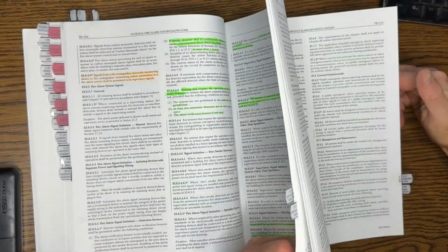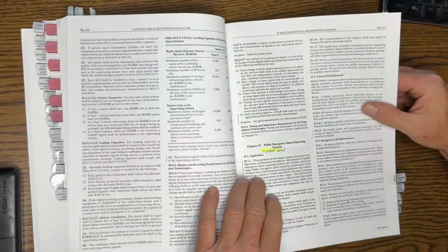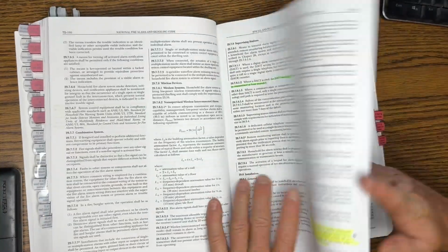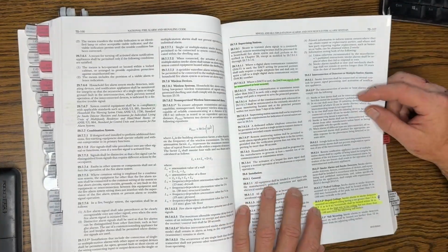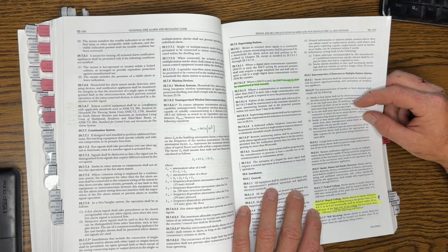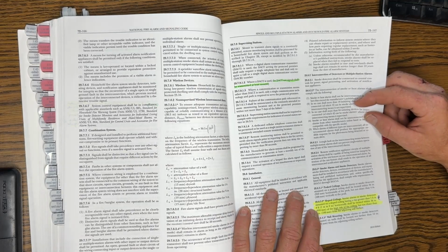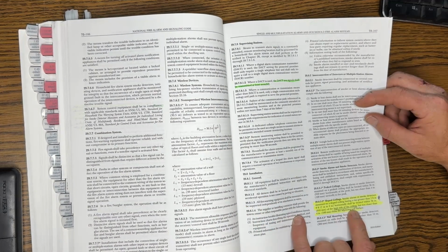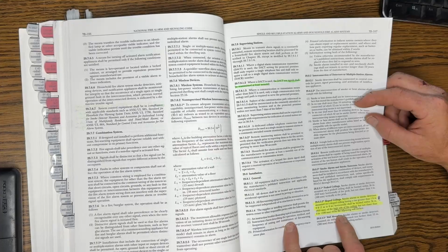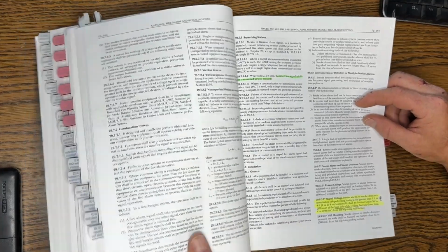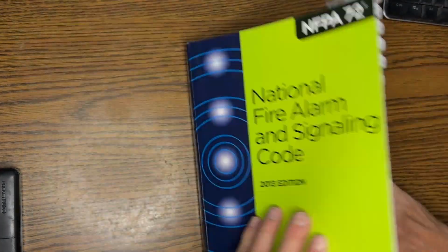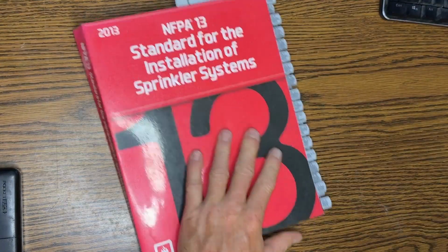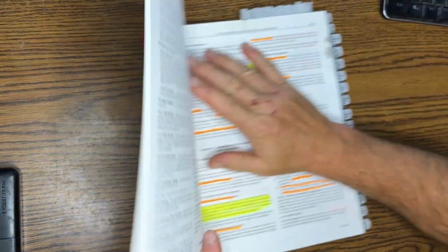I think these chapters, I didn't have anything. All right, last question for this was slope ceilings. Smoke alarms or smoke detectors mounted on a slope ceiling with a rise greater than 1 foot in 8 horizontally shall be located within 36 inches of the high side of the ceiling, but no closer than 4 inches from the adjoining wall. Okay, that's NFPA 72. Let's take a look right now at NFPA 13. See if we can slam this out really quick for you.